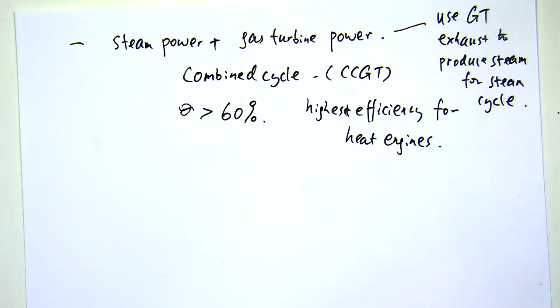To give you some conditions: the inlet condition of the gas turbine, the pressure ratio of the compressor, and the turbine inlet temperature, which is the highest temperature in the gas turbine cycle, 1100 C. It also says the compressor and the turbine are not 100% efficient. So that's the gas turbine side.